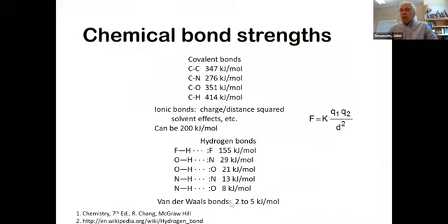So there's a huge multiplier on the van der Waals bonds. And it turns out that if you do the math, the total sum of the van der Waals bonds is usually much greater than the sum of the hydrogen bonds. Not always the case, of course, and the hydrogen bonds are important. So when we want to make an adhesive to get a high adhesive bond strength to glue our wood together, we want hydrogen bonds, but we've got to have van der Waals bonds too.